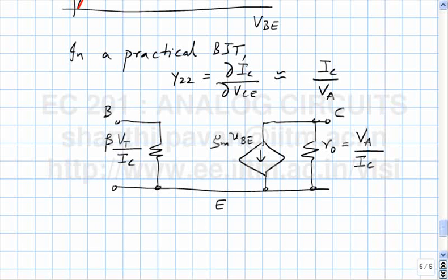And just like in a MOSFET where we saw why the characteristics must be the way they are, the same thing follows for a bipolar transistor. The DC potential between the collector and emitter must be some minimum voltage to get into this region where the characteristics become flat. This is exactly analogous to a MOSFET.